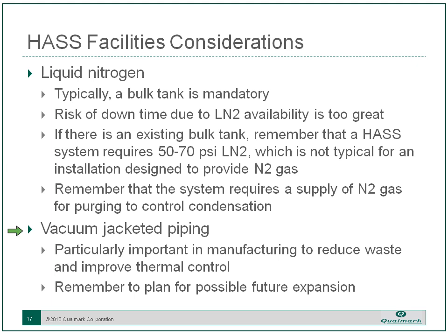And to get that in to the chamber from outside, it essentially demands vacuum jacketed piping. Vacuum jacketed piping, for those of you who aren't familiar with it, is built like a thermos bottle. There's an inner pipe, a vacuum, and an outer pipe. And it is very effective for transporting cryogenic liquids. It's also more expensive than a copper pipe with insulation wrapped around it, but it gives you a higher quality nitrogen. There's 2 key advantages to going with vacuum jacketed.